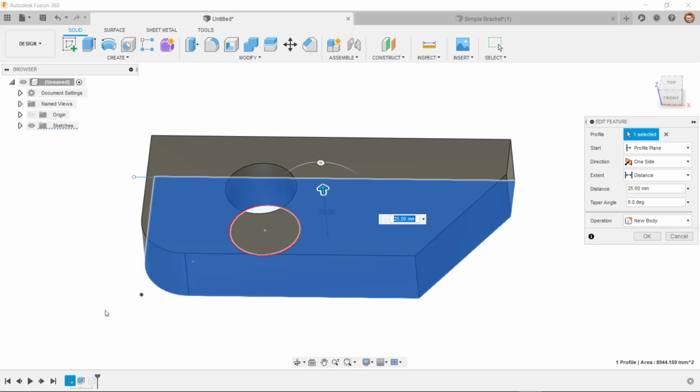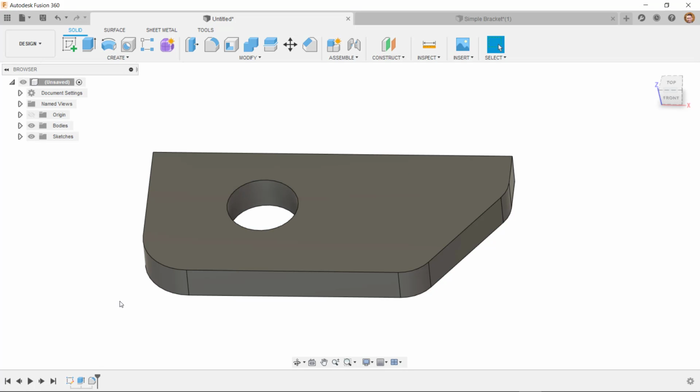This is a very powerful capability when modelling, especially in cases where you may need to go back and make small changes to the design later on, which can be very common when prototyping using additive manufacturing methods. One way to get even more control over this is by using parametric modelling. This will allow you to control dimensions and values using defined parameters, so that if edits to the model are needed, you can control these using the parameters, rather than needing to go back and change every value.